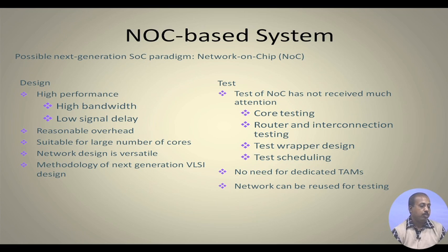Core testing was there in SOC design, and it is there in NOC design as well. So the test data volume and test transfer time are not going to reduce. Apart from that, we need to test the routers and interconnect.